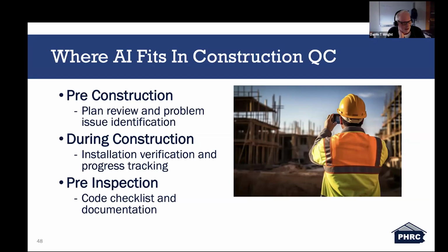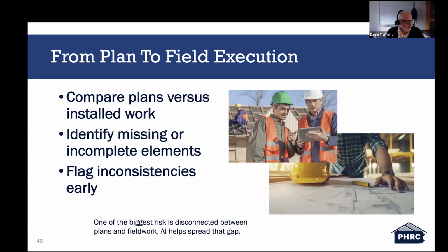And where does AI fit in quality control? It fits in at multiple stages. Before construction, it starts at the plan review stage. And during the construction, through the progress monitoring of the entire construction process. Quality control can also come into the pre-inspection through readiness checks. This layered approach helps reduce risk by catching issues early, and they are easier and less expensive to correct, improving overall project outcomes.